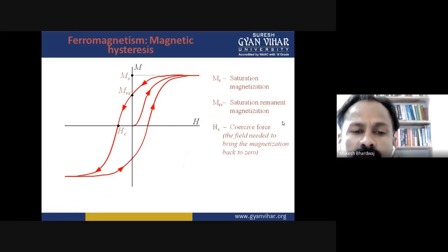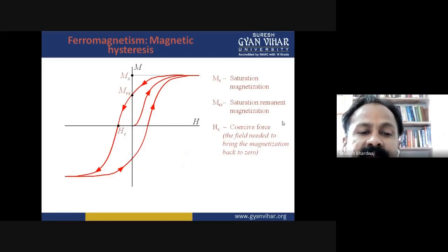For example, barium ferrites are the most important type of ceramic permanent magnetic materials. They have much higher values of coercive force than alnico alloys. They have high resistance to demagnetization, about 3 times more, and high electrical resistivity, about 10^6 times that of alnico alloys.